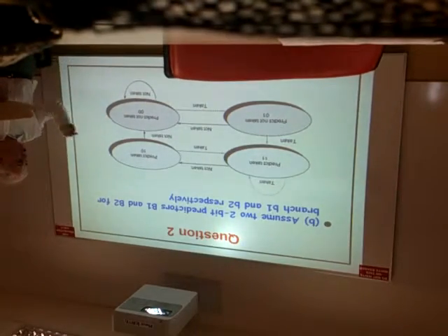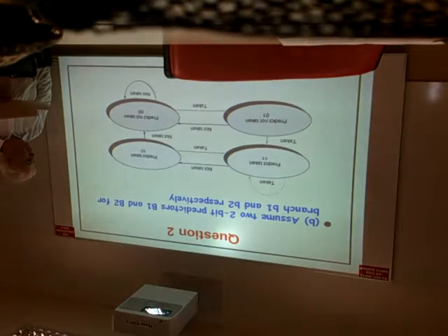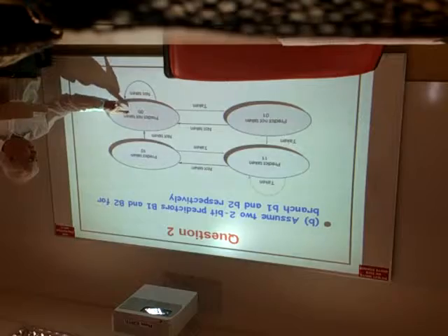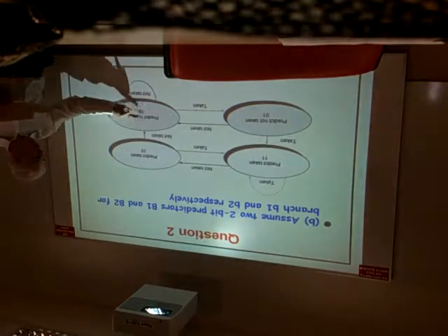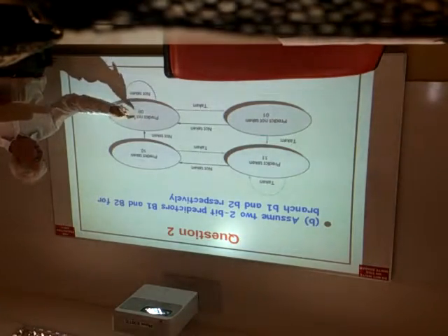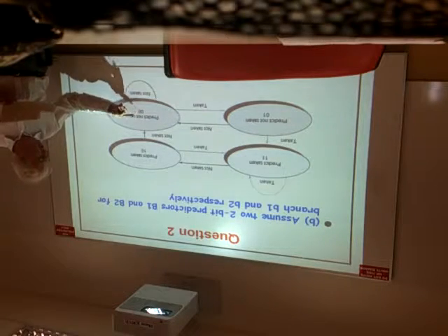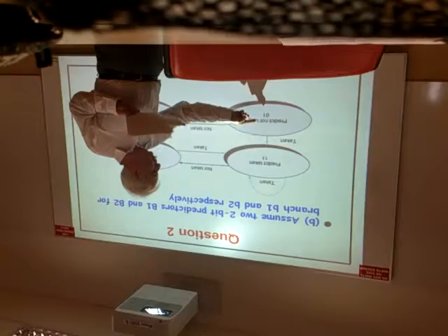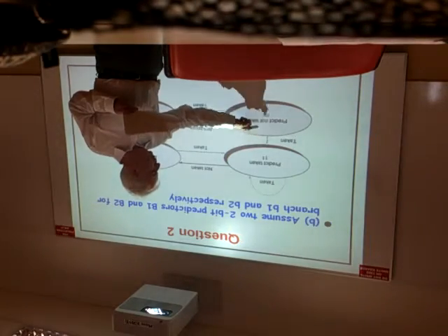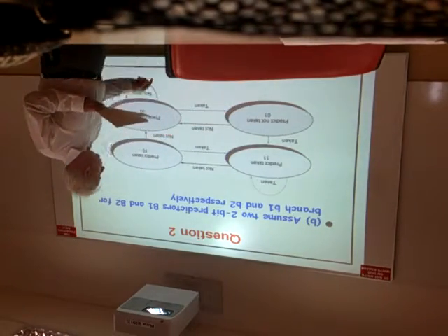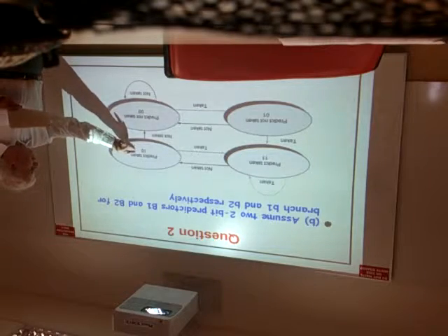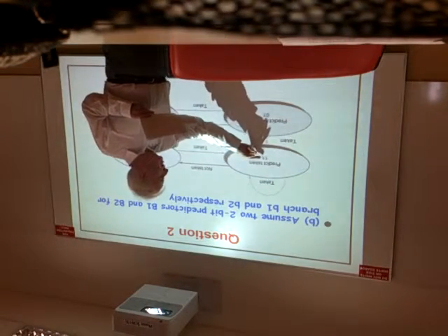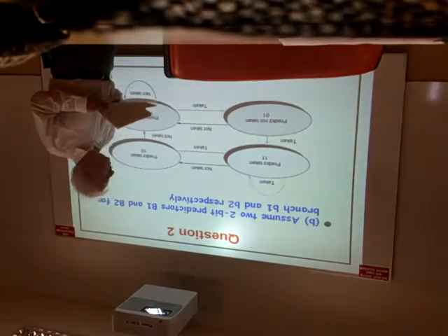And this shows the transitions between the different states. So for 0, 0, we predict not taken, and here we're fairly confident about the result. 0, 1, we also predict not taken, but we're not so sure. 1, 0, we predict taken, again we're not so sure. 1, 1, we predict taken, and we're more confident.